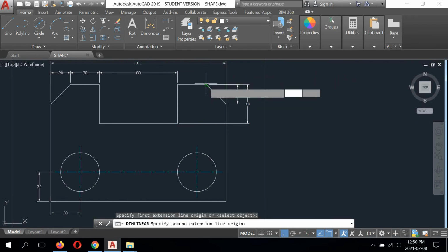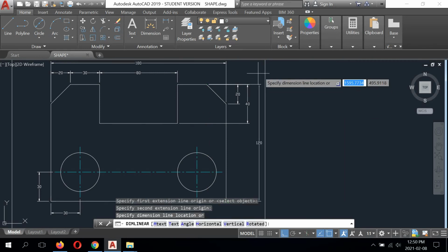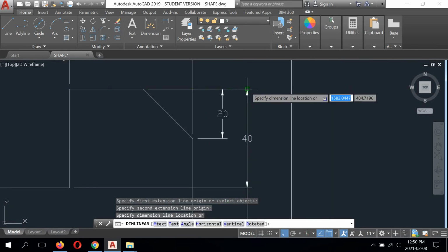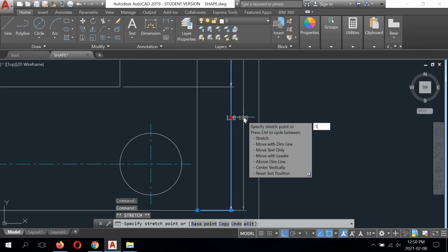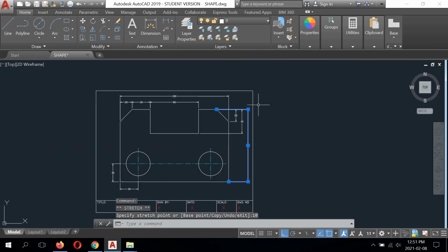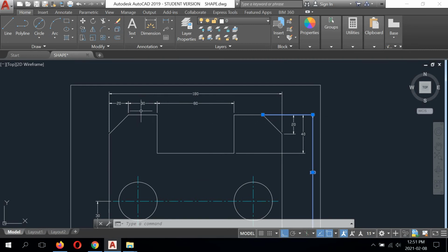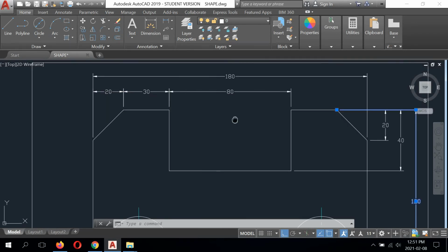There's one more to do on this side. So we're going from here to the bottom end point. Snap in line with the 40. And again, 10 millimeters. If I actually have to do another set, it would be 10 millimeters as well. The only one that's furthest is the 12 millimeters. That's the first stack. If I had a second, third, fourth, fifth, I would continue just to go in increments of 10 millimeters after my first set.